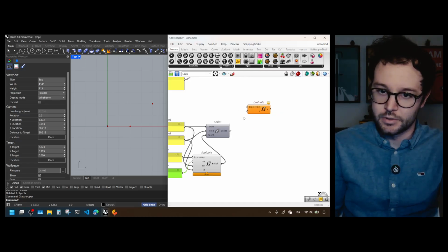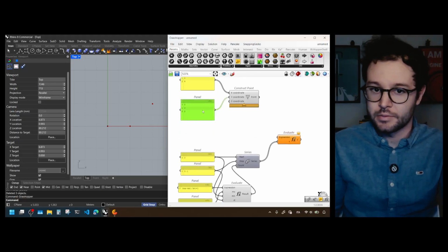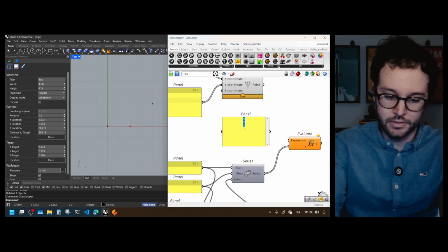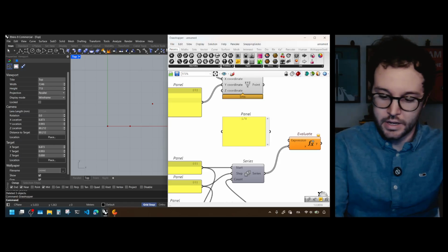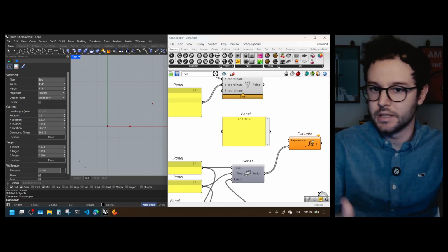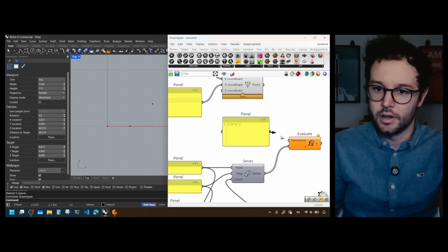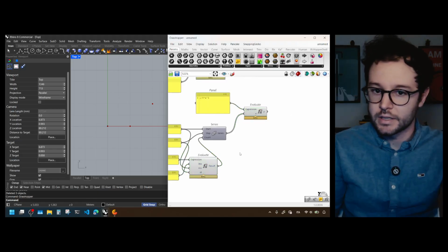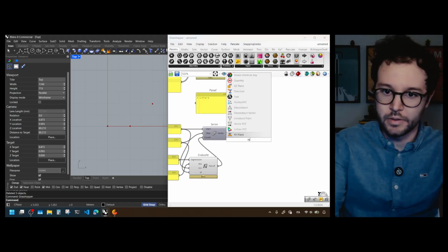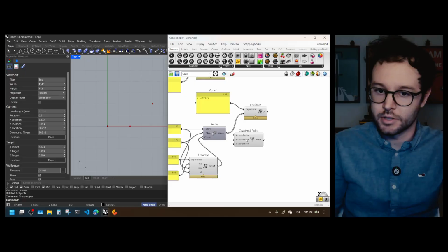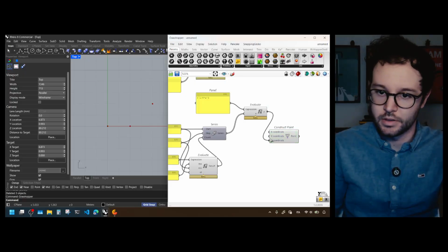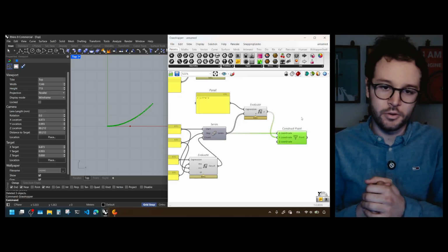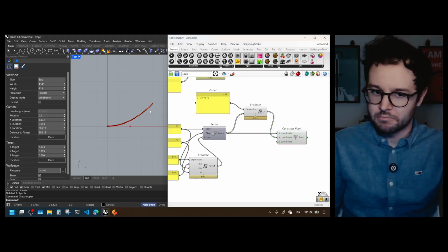We drop it in, and indeed we get a series between 0 and 4 in increments of 0.1. So let's drop it into, not the expression, but x, and then the expression is the parabola we found, which is y. So y is already set, we don't have to repeat it. It's 1/8, because that was a, times x squared, b 0, c 0. So this is just our function. So we get the corresponding y's, and now that we have y and x, we can just plot them using a Construct Point. Let's do this with points. So this is y and this is x, and indeed we get the parabola between 0 and 4, which passes through the points, which is quite interesting.